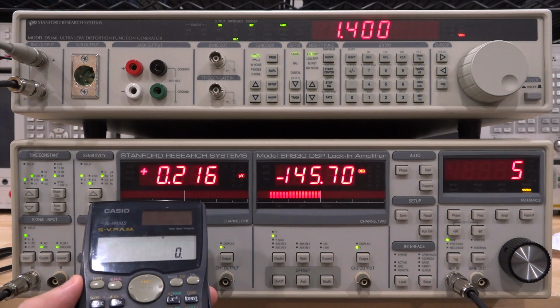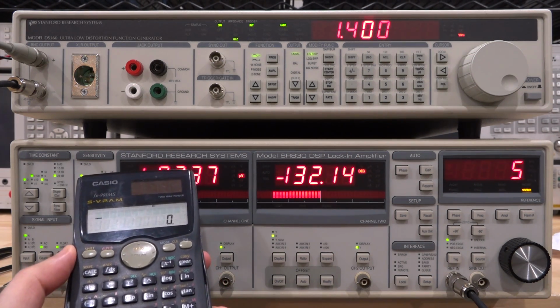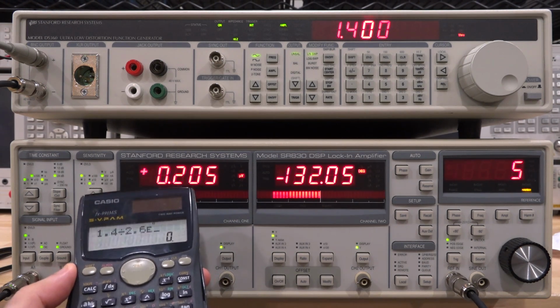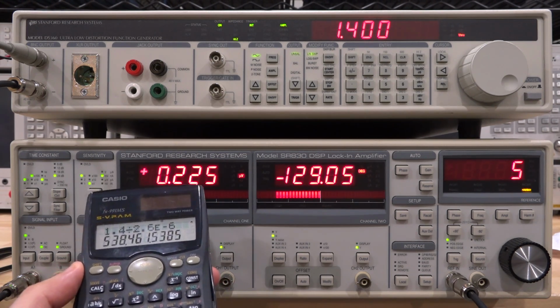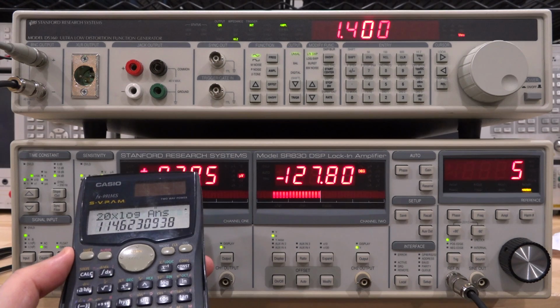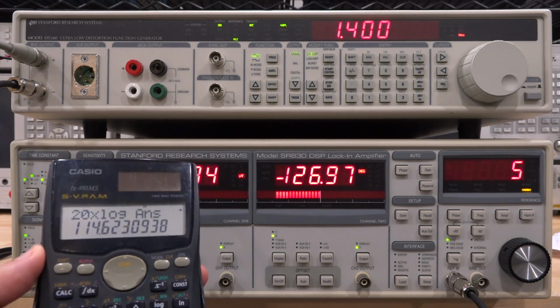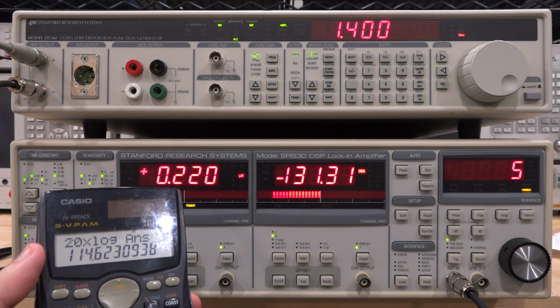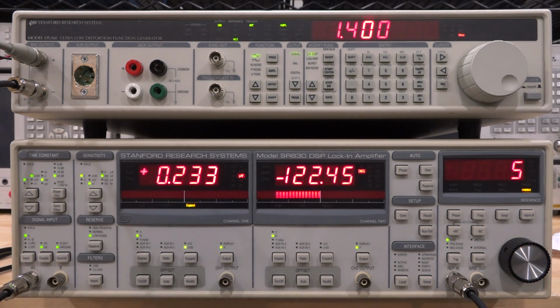So the signal coming in is 1.4 volt RMS, so 1.4 divided by the signal I just mentioned, 2.6 times 10 to the minus 6, and that's the ratio. If we do a 20 log of that, what do we get? 114 dB is the THD, and the spec is that you're typically supposed to get better than 110, so this is definitely meeting that. And there's some other calculations you can do, even higher harmonics. There's a little bit of power in there too. If you calculate those, you'll probably end up around minus 110, which is what you would expect, which is amazing.